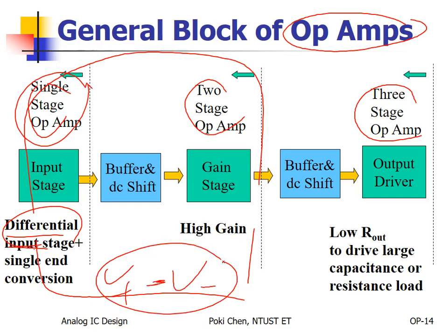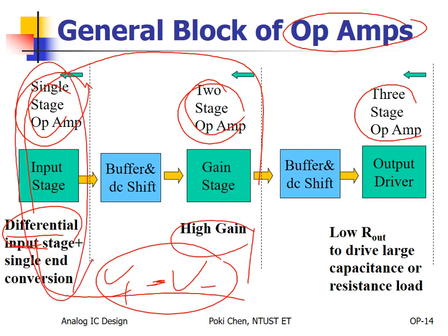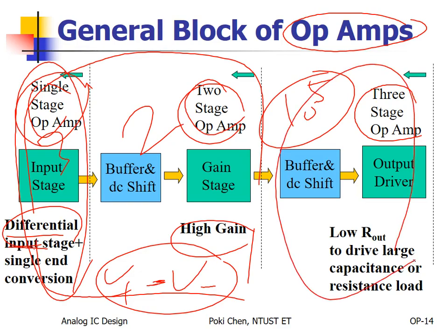And then the second stage is the so-called high gain stage, but the differential amplifier will provide the most gain. For example, if you do a very good design to get 5 orders of amplification, usually 3 orders for the first and 2 orders for the second. And then finally, this stage is used to drive the load. It means what? Large enough driving current. Okay, that's it.